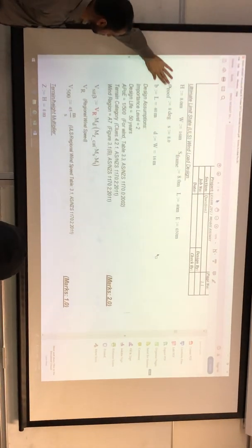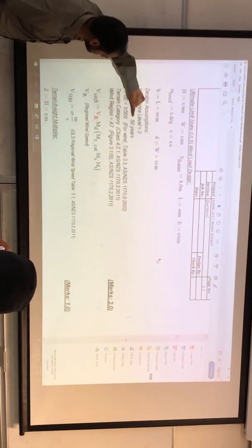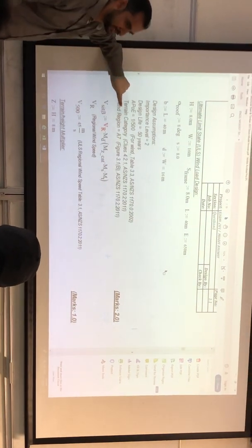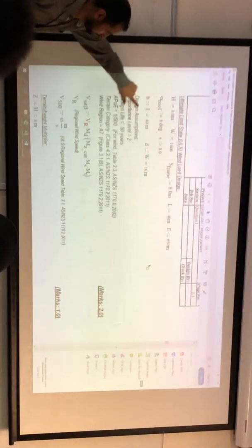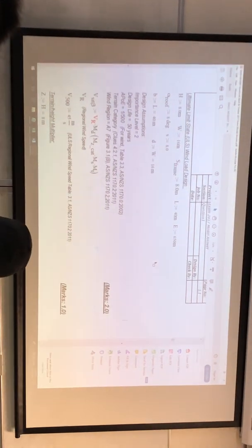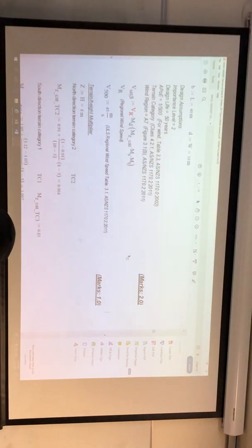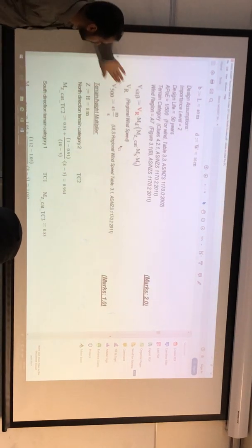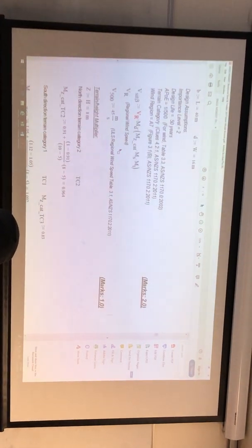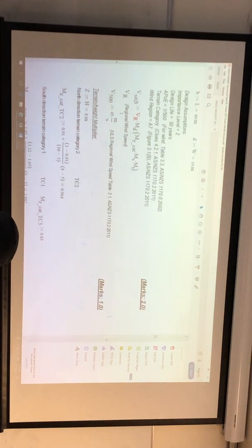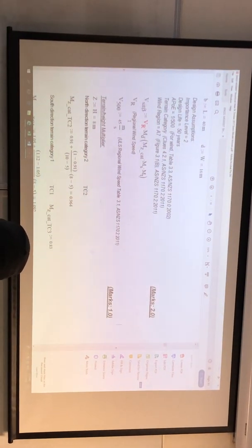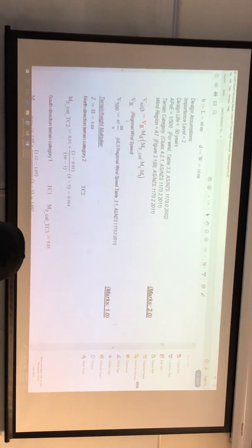So all I need to know, okay, that's important to me. Then this one, terrain category, of course, you will go down and do it. If you have done that, you get the 2 marks, and the building dimensions. Then the next is the formula. If you write the regional wind speed, it's another mark. In this case, we got 45 because it's Christchurch, and Christchurch is A7, I think. A7 or A6, one of the regions, but yeah, it's A7.